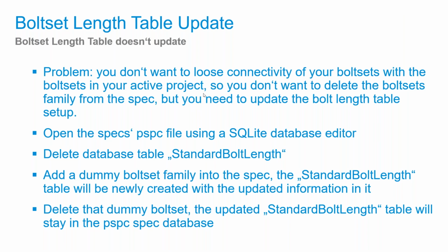So in this case, if you don't want to lose connectivity of your bolt sets with the bolt sets in your active project, you don't want to delete the bolt set family from the spec, but you need to update the bolt length table. That's the situation. What we found as a workaround is that you can open the spec's PSPC file using an SQLite database editor. You delete the table standard bolt lengths, and then you add a dummy bolt set family in order to get the bolt tables imported again.